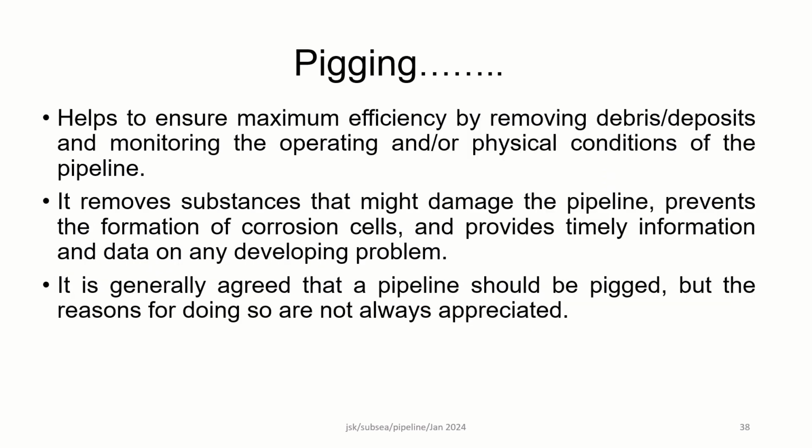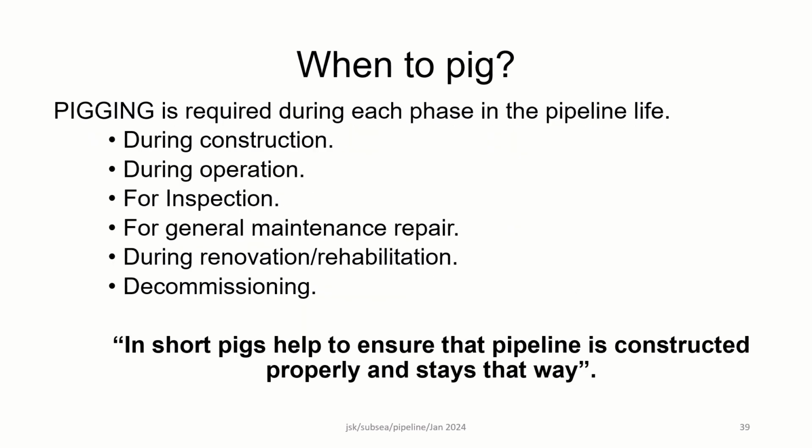Normally pigging helps the way it helps for onshore pipelines. It helps us to know the health of the pipeline by analyzing the debris or deposits recovered from the pipelines. Pigging, as we understand, is to be carried out throughout the life cycle of a pipeline, right from the construction phase to the decommissioning phase.